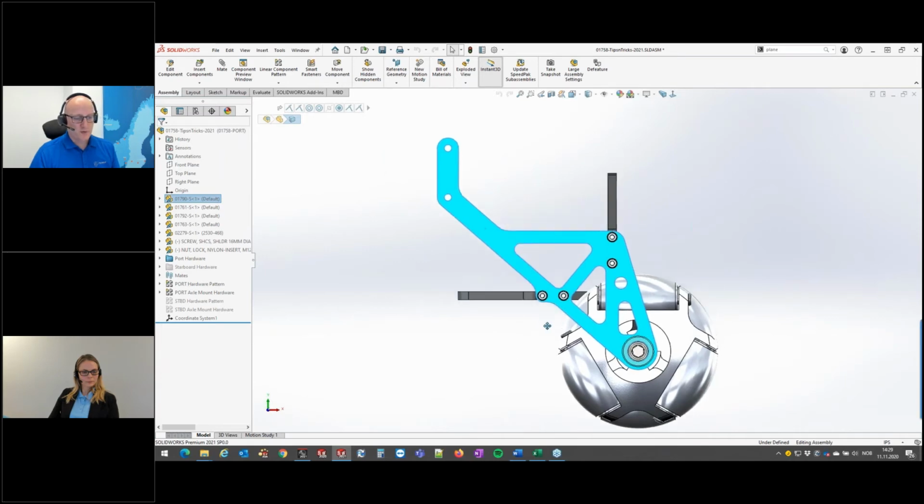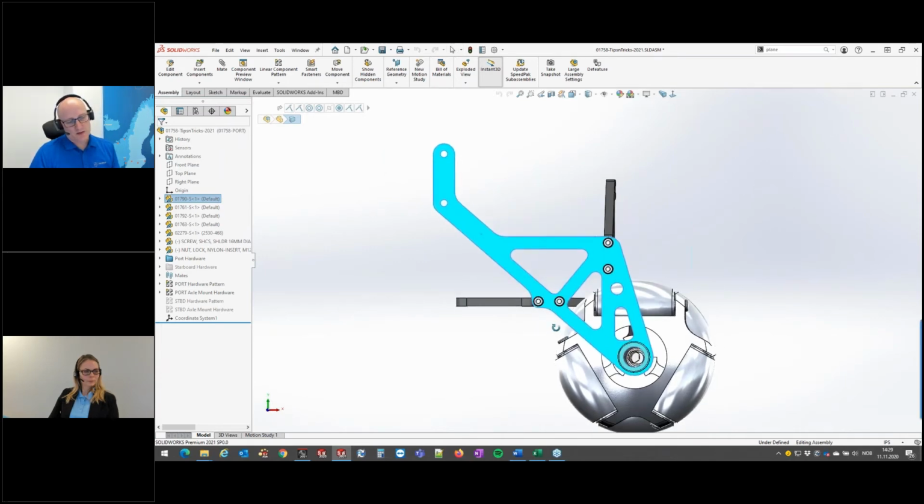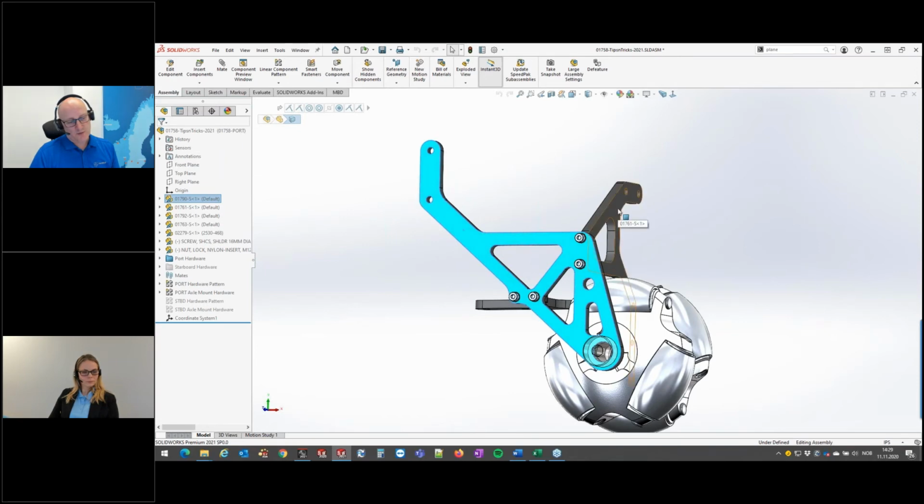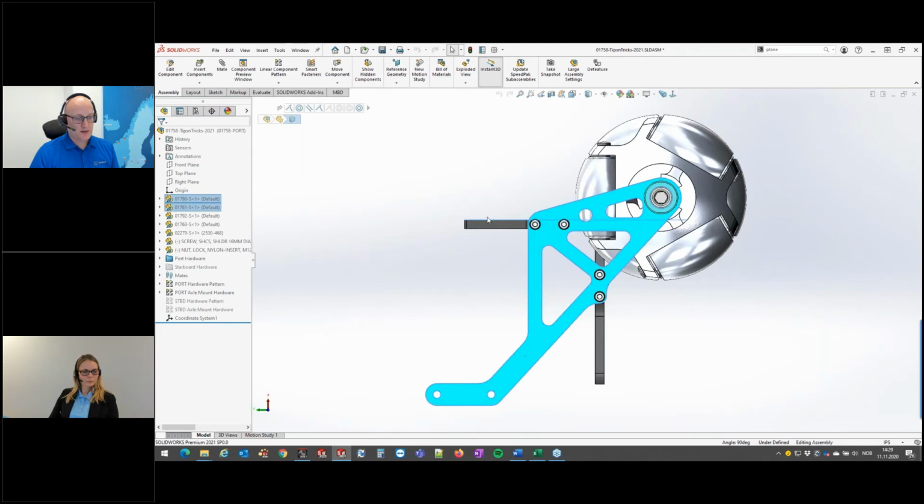What you might not be familiar with is that you can actually click a second face. If I press this face, then I will orient the model a little bit differently. Still normal to this first selected face, but I will use the second selected face as an up direction when I orient the model. So this can be used to sort of force the model to be rotated exactly the way you want.